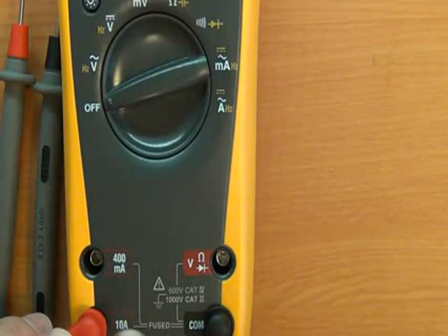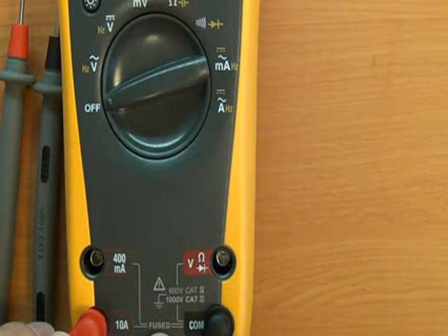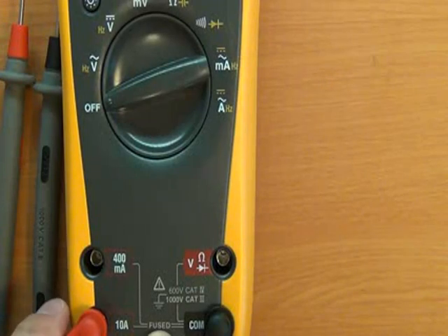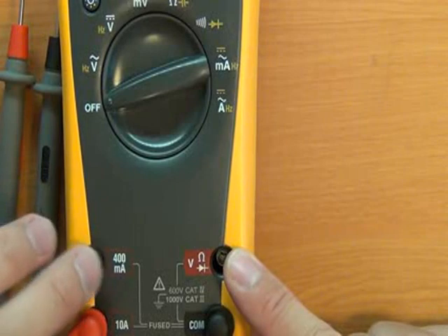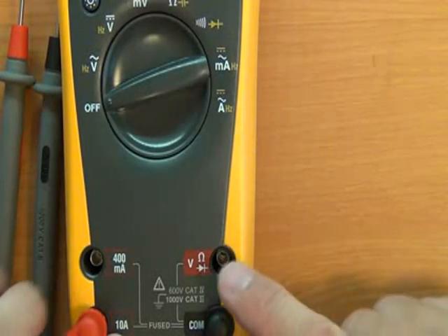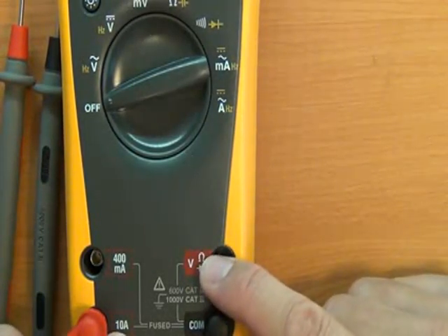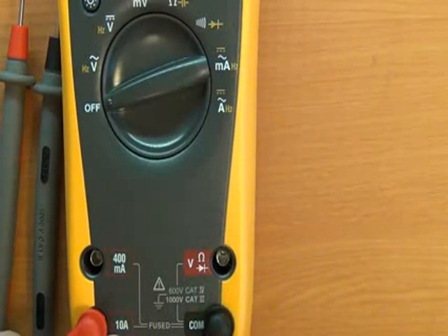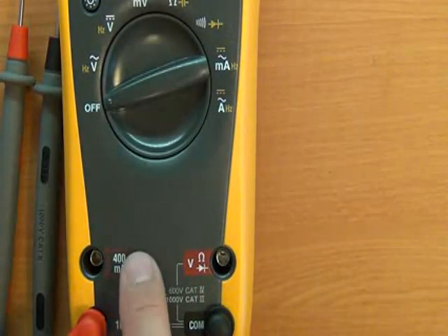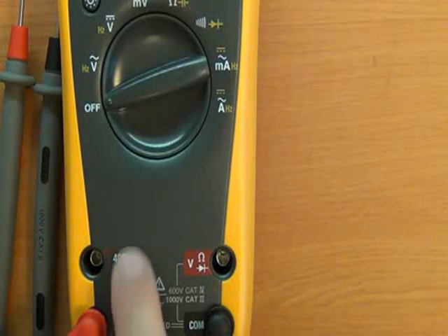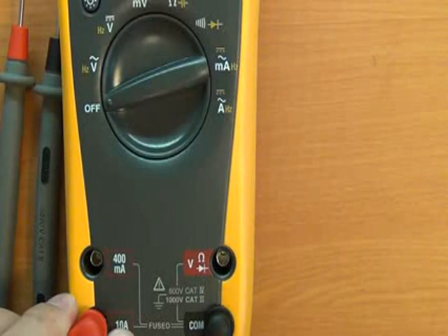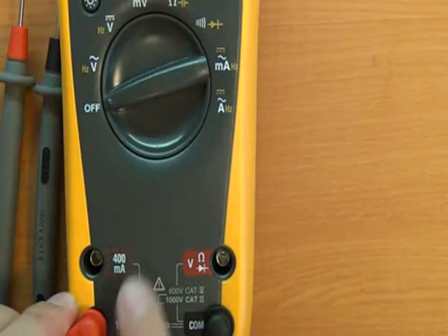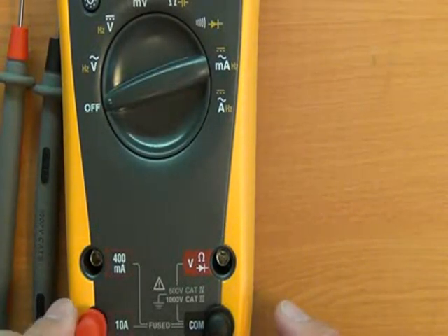I would advise that if you own an existing multimeter which isn't fused, I would recommend getting one that's fused. I'd also recommend getting one that definitely has separate plug connectors for your current, and it's not shared with the voltage, and we'll cover why a little just now. But having fused points for your milliamps and your amps is important. As I said, always start on the higher one. When you realize your current level is safe, you can then flick down to the lower one.